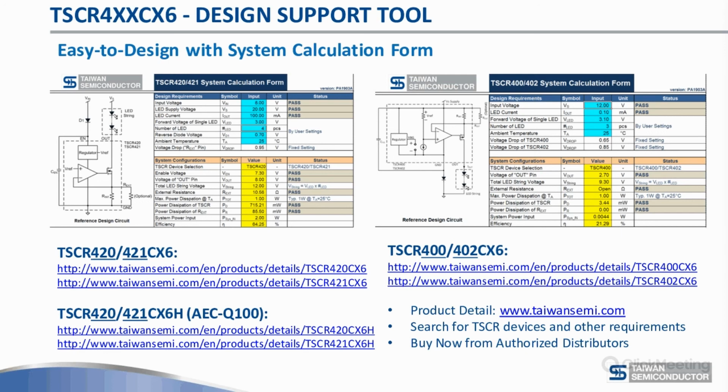The total output dissipation is of course also dependent on the PCB layout and the thermal resistance of the PCB. And the last thing that you need to be able to calculate is the resistor you need to put in parallel with the internal resistance to increase the current.